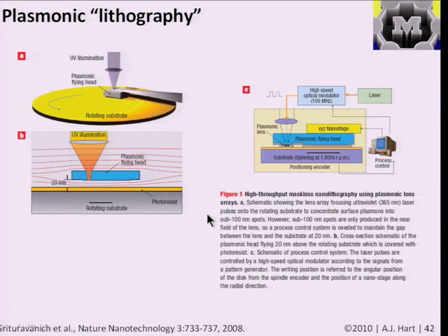And the idea advanced by this recent paper is that because we can get very strong local fields and basically focus light beneath its wavelength using this plasmonic effect, we could possibly use a substrate of nanostructures, say nanoparticles or a metal film with holes, to create very strong and small fields of light that could be used to do lithography.